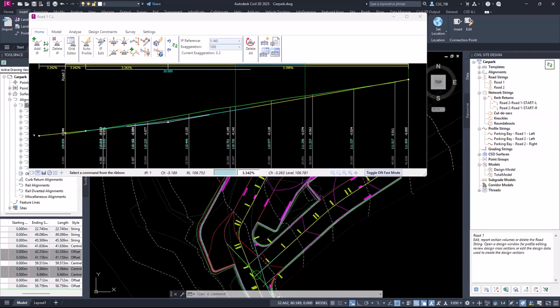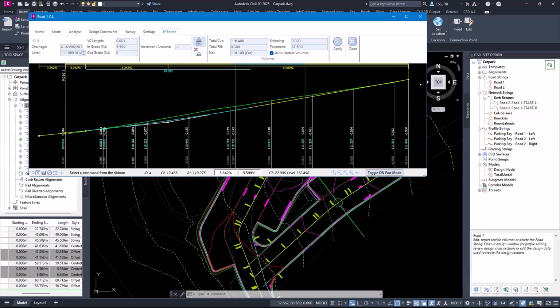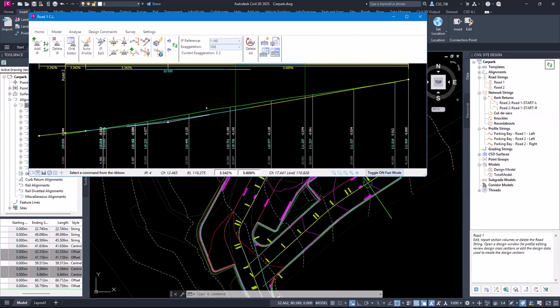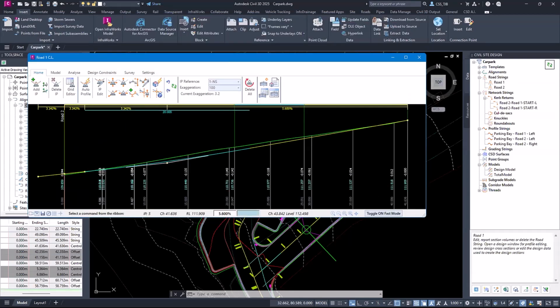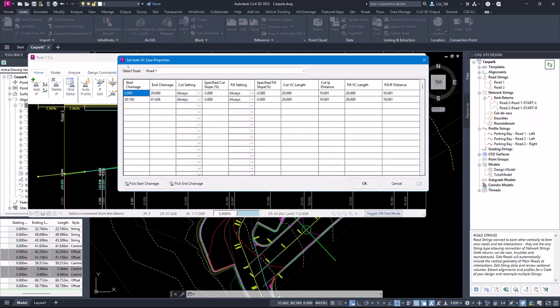You can see here it's projecting the one-way crossfall in, but then it's adding in my ease controls in here, which I didn't play with the settings. So I need to play with that first, probably. I also probably, same deal here, need to anchor that to the terrain model. So ease controls or side road matching, depends on which part of the software you look at as the name we give it, is controlled on a road by road basis.